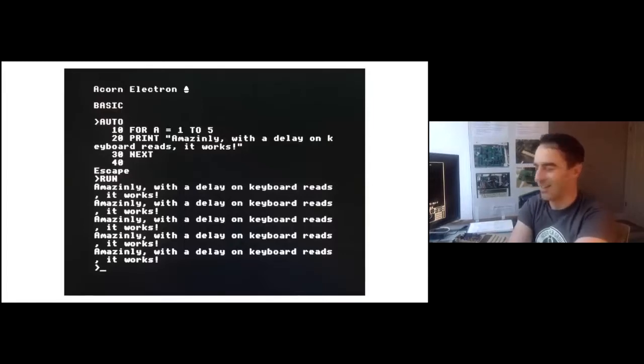And I was pretty daunted by the buffer situation, but it turned out that there was another buffer in the same package. I thought I'd been very clever by finding this BGA package. It made it possible to make this very small board. And then I thought I'd painted myself into a corner by making it so I could only use these buffers that weren't going to work. But it turned out that normal buffers, 74LVCs, were available in that BGA package. So I got a few of those and soldered up another board.